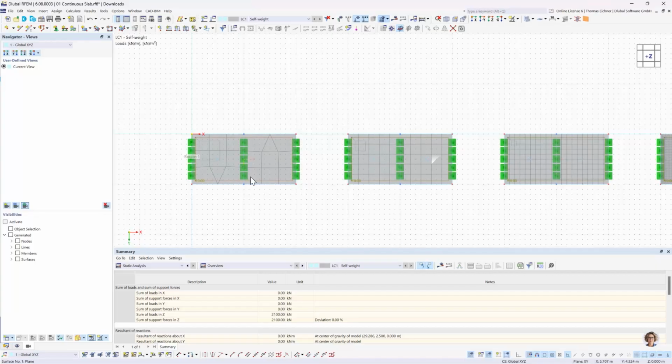So in the first model, with our 2 meters length here, well, that's quite coarse. And we also see we even have a triangular element here, which is also never perfect, since it's just better to have a uniformly distributed rectangular finite element mesh.